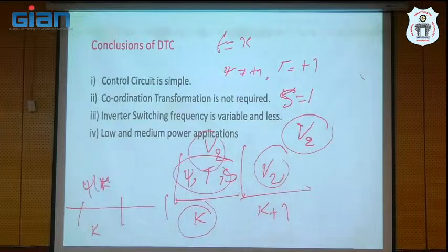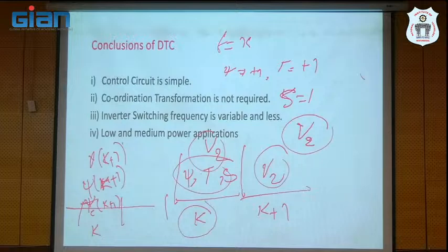What is the nature of the flux state in the coming sample? What is the nature of the torque state for the next instant? So what is the required voltage vector for the next instant? They will predefine it, right? This voltage vector they will apply at k plus 1. Whatever voltage they select for the k plus 1 instant, that voltage is 100% responsible. That is the logic behind model predictive control.